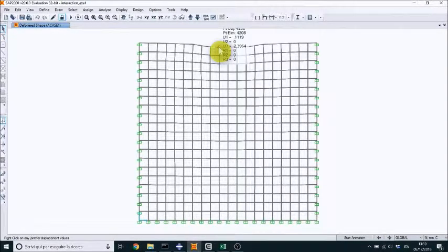So when you insert an element over your soil, you have to be sure that the ratio between the rigidity of your foundation and your soil brings you to the creation of a rigid or a flexible foundation.